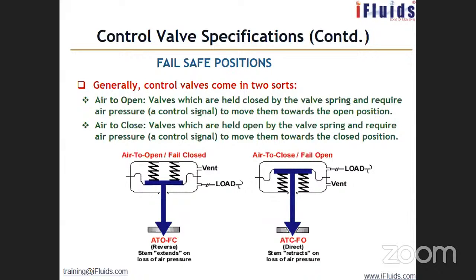Cavitation means the valve is designed for liquid flow, correct? If it sees both liquid and vapor, the valve will be struggling. It doesn't know what to do. So that is cavitating, and flashing is because of the boiling of the liquid. Vaporization of the liquid is flashing.